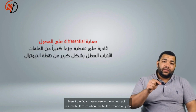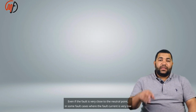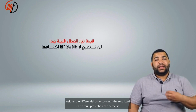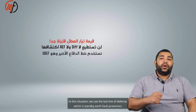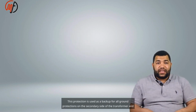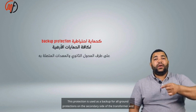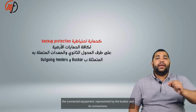Even if the fault is very close to the neutral point, in some fault cases where the fault current is very low, neither the differential protection nor the restricted earth fault protection can detect it. In this situation, we use the last line of defense, which is standby earth fault protection. This protection is used as a backup for all ground protections on the secondary side of the transformer and the connected equipment, represented by the bus bar and its connections.